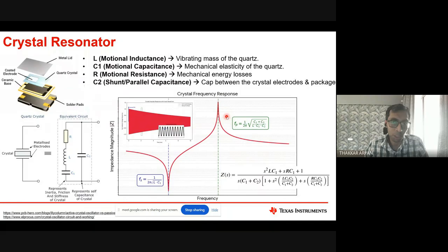First, it will be more susceptible to noise. I mean, I am not introducing noise, but phase noise will be very bad, because for phase noise to be good, its quality factor has to be really, really high. And the higher the quality factor, it is very difficult to move it from one side to another side, right? See, imagine like this.